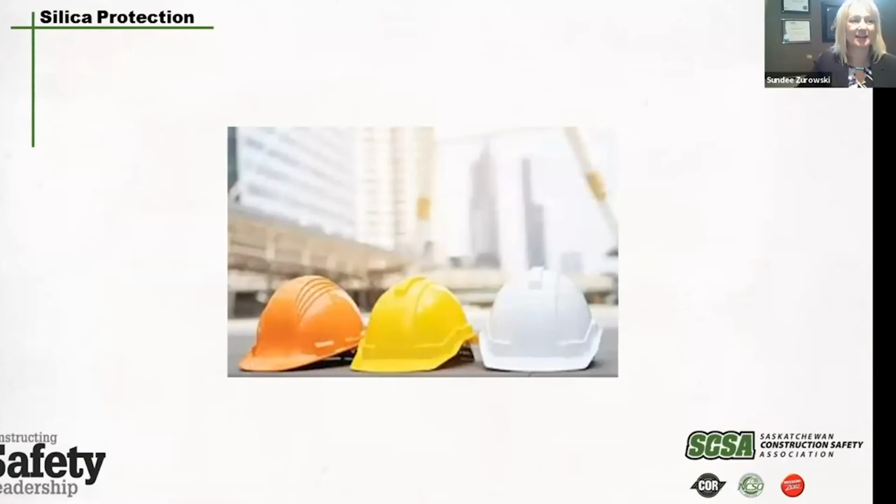Okay, so engineering controls. Always refer to the hierarchy of controls and consider engineering controls first. There are a few different ways of keeping dust levels down on your construction site, which in turn will keep silica particles from becoming airborne. Engineering controls are mechanical processes used to eliminate exposure to dust. Engineering controls remove the dust from the air or provide a barrier between the worker and the dust.